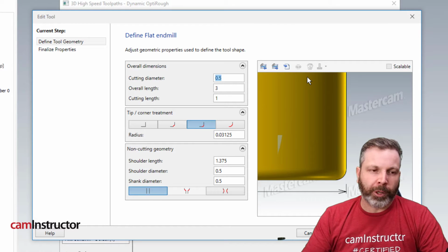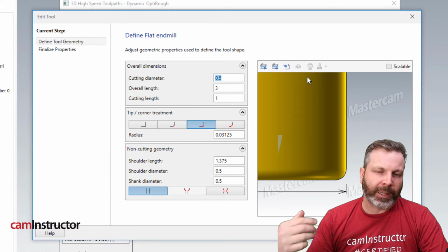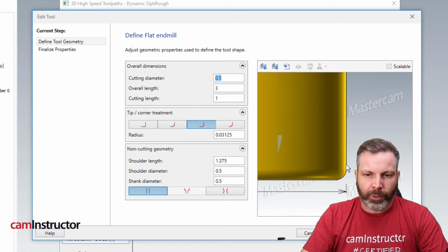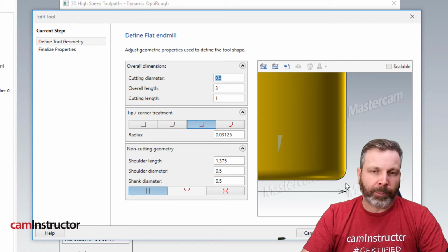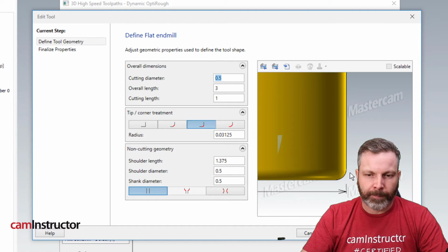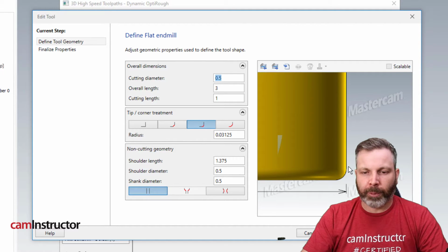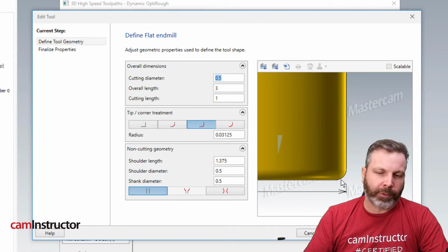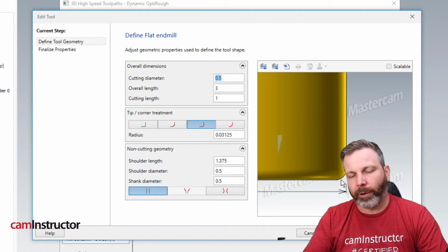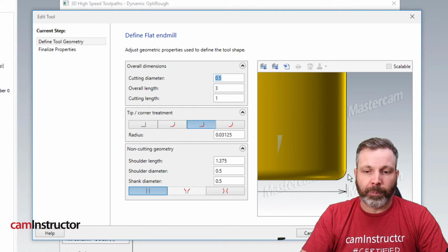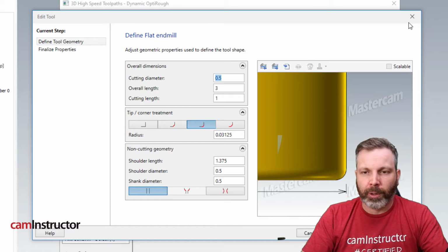Especially if you're roughing, you're wanting to push that tool hard, cut material, get it out of the way as quickly as possible. So you're putting a lot of stress into the tool, and if you have an exactly sharp corner tool, that point becomes a weak spot on the tool, and that's where the tool is going to fail. It will break into some obscure shape on this corner, and it will not cut optimally. It's going to create excess heat. Excess heat makes tools fail quicker.